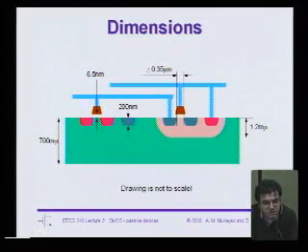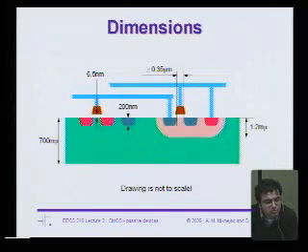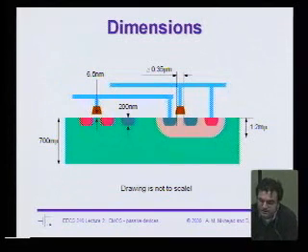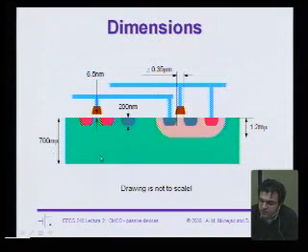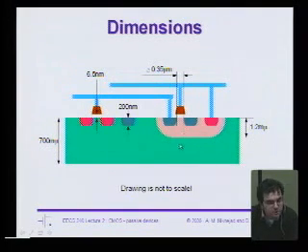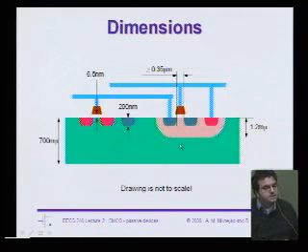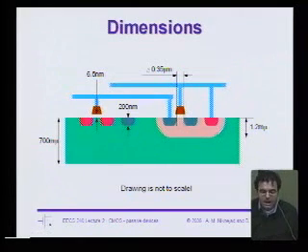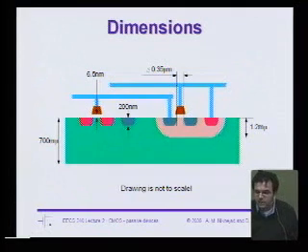There are other applications for thinning the substrate. One is to have flexible chips. If you make this thin enough, it's flexible, and then you can put it on contours that are not flat. Other applications are for taking one process and housing in another. So for instance, if I don't like this conductive substrate, then I could thin it away and then mount this onto another wafer that has a different resistivity, let's say a higher resistivity, where I could put passive devices that have better quality factors.